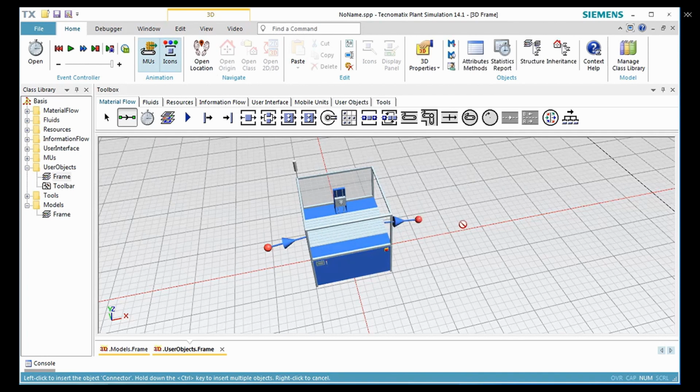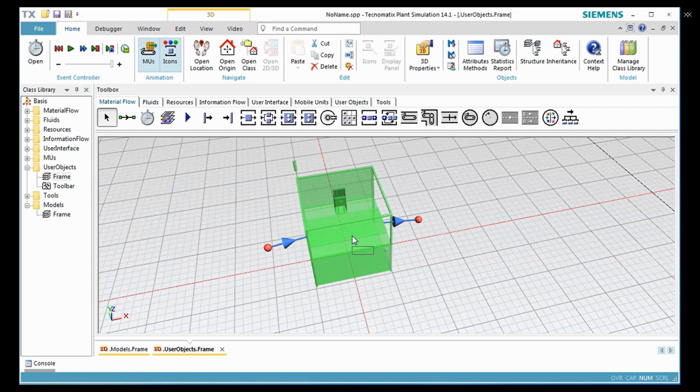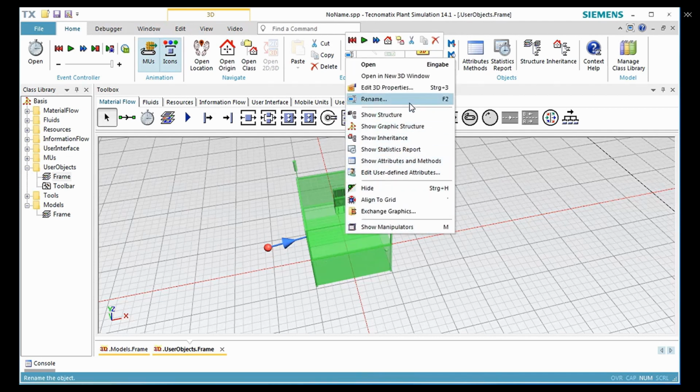In our station, we want to move the tool holder from the position in the center to the right end and then to the left end and then back to the center. After this, the moving objects or paths can leave the station. First, we have to step into the graphic of the station. Select the station, click the right mouse button and select Open a new 3D window.